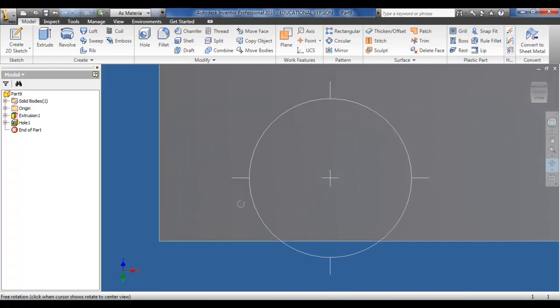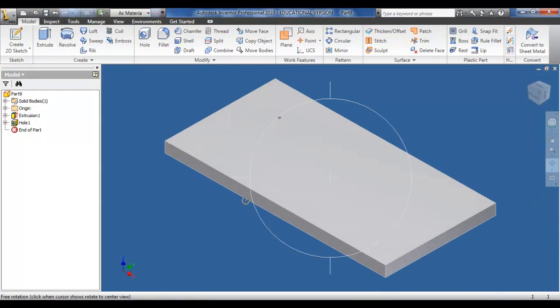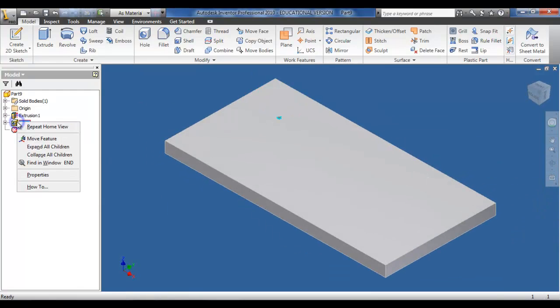And as you can see, the hole didn't come out through the block as we had set specifications to stop short. You can just go back in the hole again, and if required you can actually move the feature by simple drag and drop.